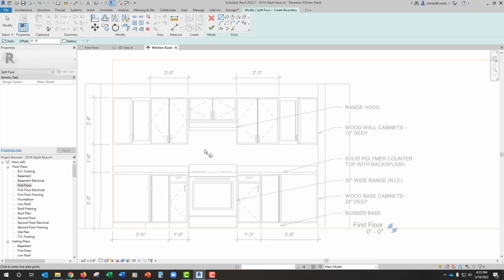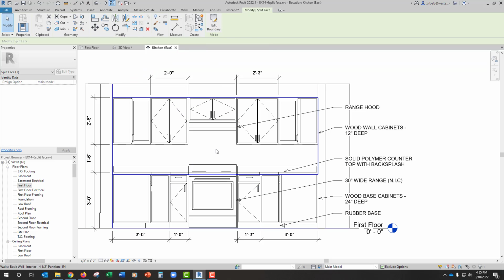I click on the wall to select it, and you can see the wall goes way up there, it goes over there, but it ends here. So I'm going to come down here, take it up to here, take it up to here, and I'm not going to go down because I can't overlap that last boundary, and then I'm going to hit done. And so now I do have that element split. Okay, so now I'm going to go back into realistic colors here.